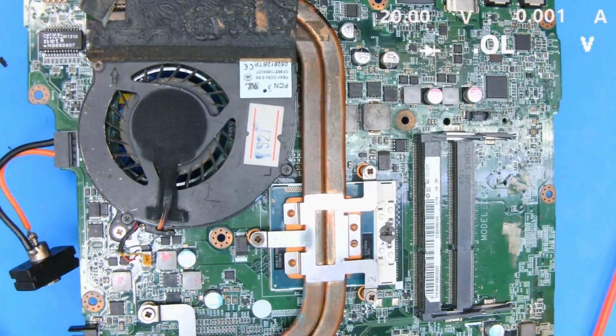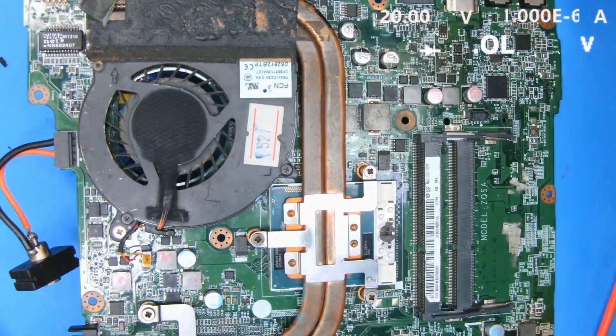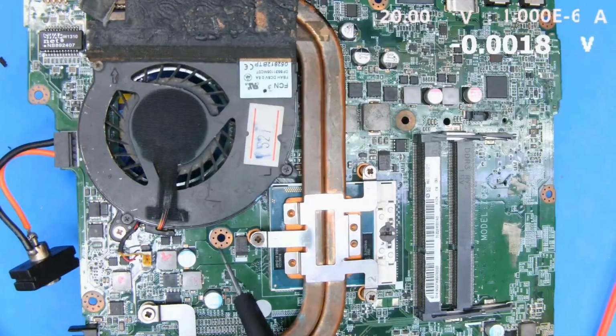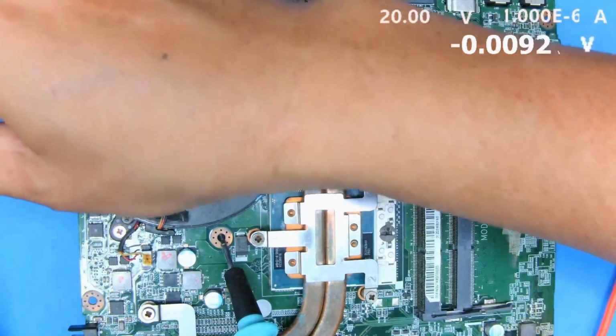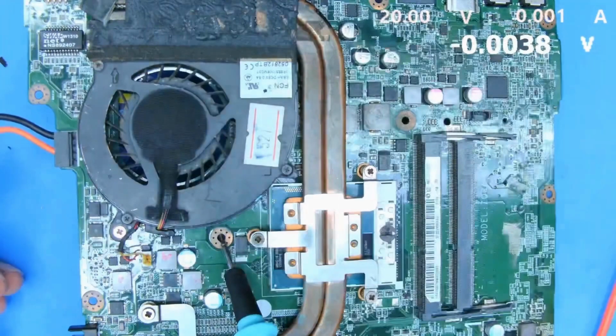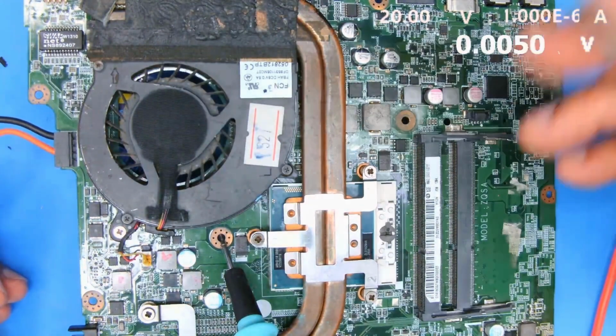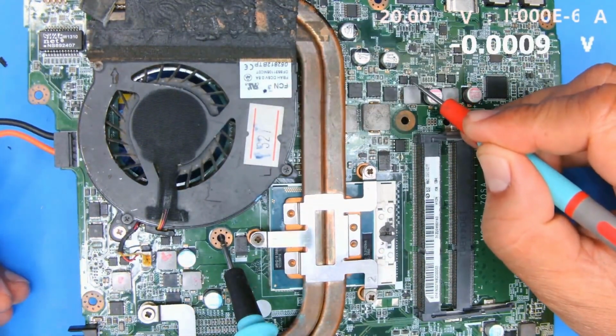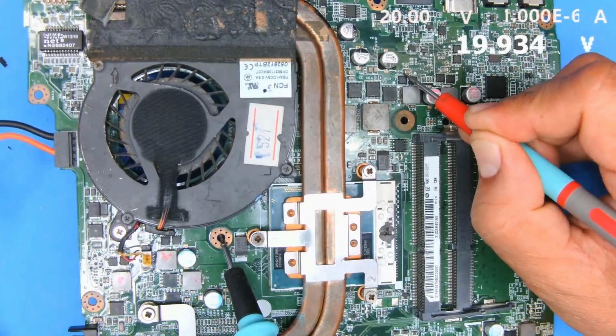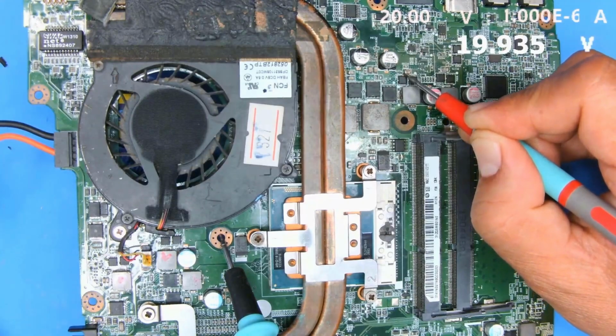Okay, so now I will supply 19 or 20 volts to measure the voltage. Set the meter mode to the voltage range. Set the meter to DC, use the black probe on ground, and measure the voltage. Plug in the adapter to supply power to the system, and then read the voltage at the 49 point. Measure the voltage at the 49 point like this. You'll get 19.9 or about 20 volts coming in. This means it has passed the high voltage system check.